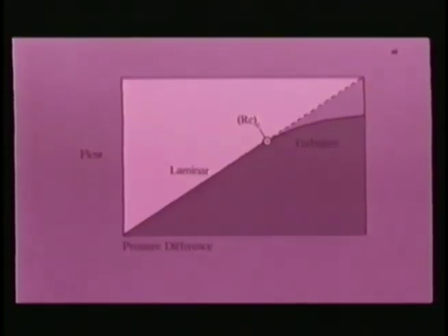40. The shape of the curve relating volumetric flow rate to pressure difference varies with the onset of turbulence. At low flow rates, when the Reynolds number is below the critical limit, turbulent resistance is insignificant, and the relatively constant viscous resistance in laminar flow results in an essentially constant slope. When flow exceeds the critical limit, turbulence begins. The addition of turbulent resistance to viscous resistance raises the total resistance, causing the flow rate to fall below that predicted on the basis of a linear pressure-flow relationship.